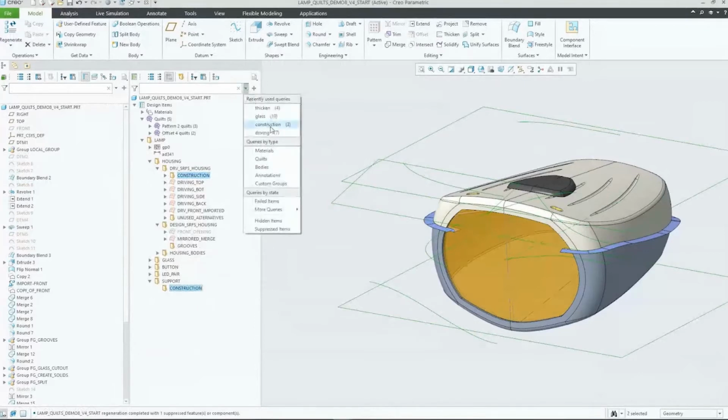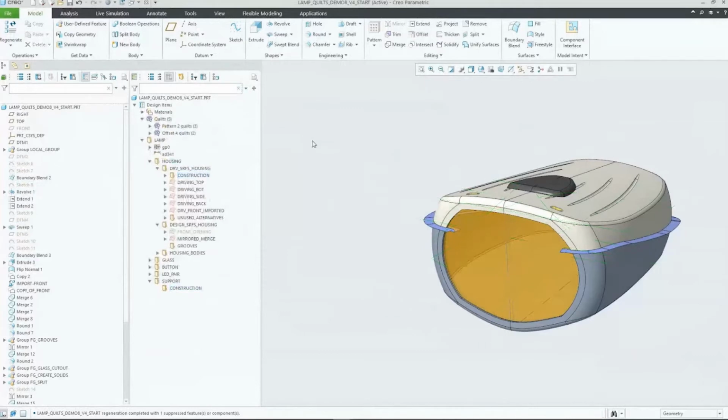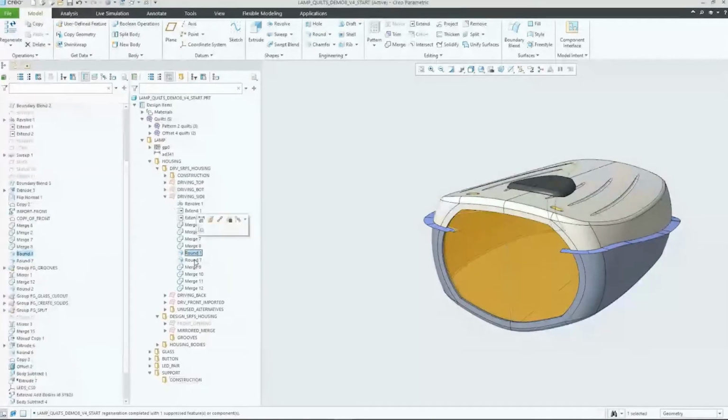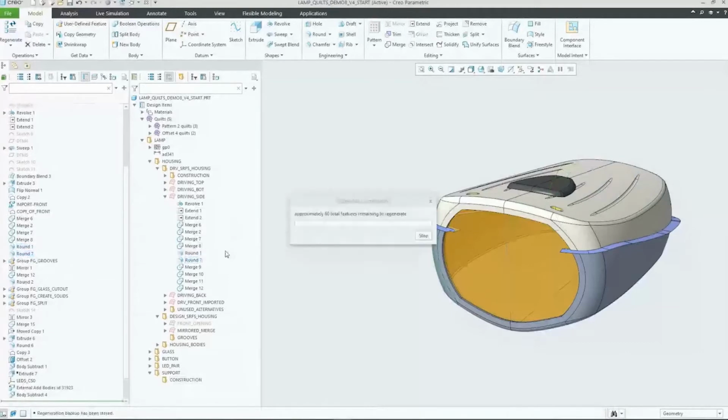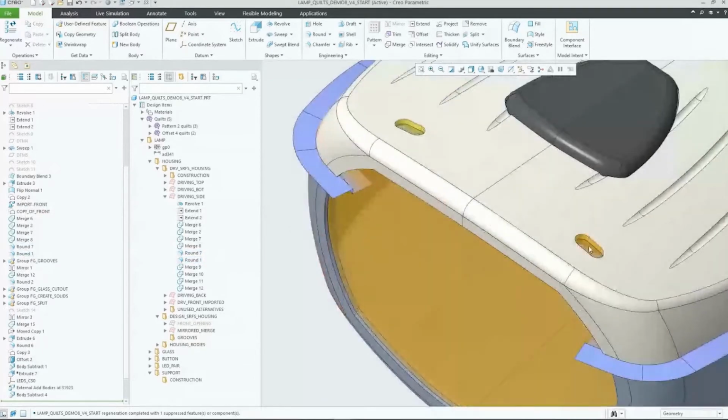And you can have multiple similar names in the groups. So you're not limited by unique naming of those. So let's say you have the surfaces that go for construction, but you also have a curve that goes for construction. You can have different folders and different places in the tree as well. And if you select something, obviously something is highlighted on the model tree as well. If you want to suppress or resume either of them, it will go nicely as well. It's also possible to change the order of the features from the design tree instead of the model tree.